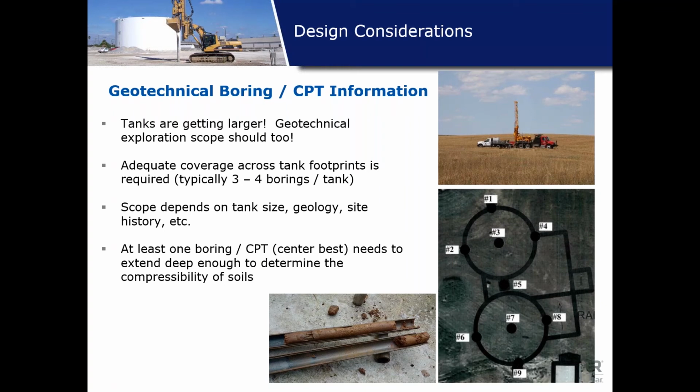We need to understand the site history of this thing, and that's why performing borings is essential, the very primary thing we need to do. It's worth investing that much money to get the information instead of just relying on the adjacent tanks, where most of the time we've been told, okay, there are these tanks, just design this tank as well. But getting the soil information is one of the critical aspects in the design of the proper foundation system.